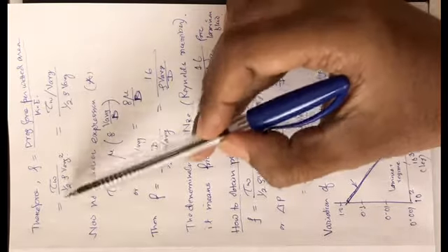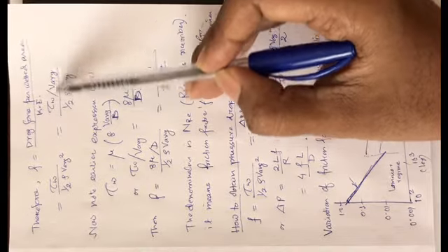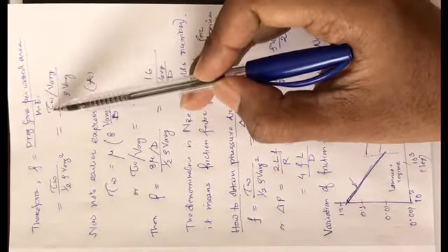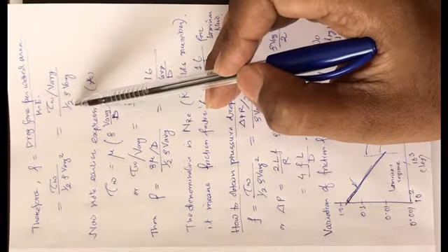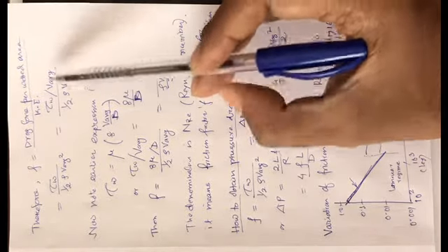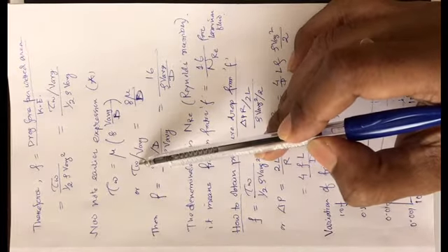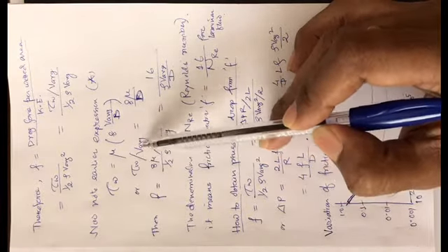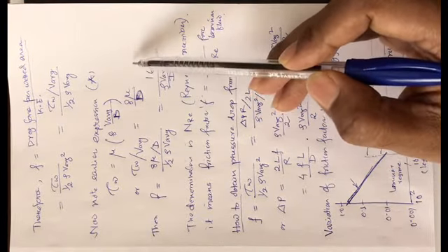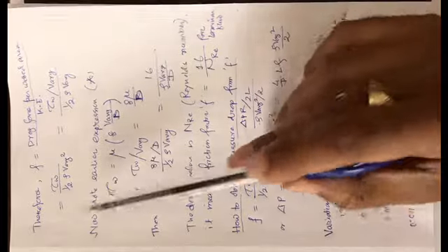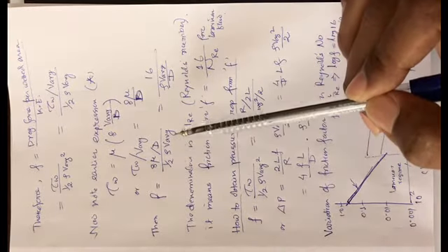Then of course this is a little bit manipulated, tau w by V average. Somewhere we have done this, no? So how are they related? Wall shear is related to V average. We know that expression also, and the denominator is half rho V average squared. So from this earlier expression you can remember that tau w, the wall shear, by V average, we got an expression 8 mu by d or 4 mu by r. Okay, so then the expression for F becomes 8 mu by d divided by half rho V average squared.